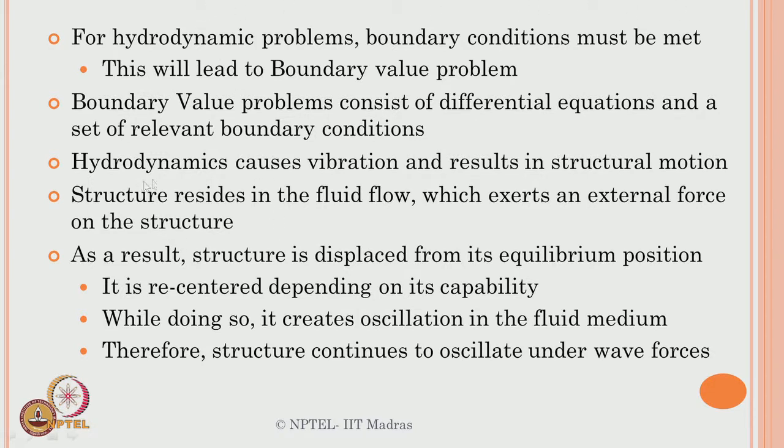Hydrodynamics actually causes vibration. The moment it causes vibration, it will result in a structural motion. The moment the structure starts moving in the regime of fluid flow, there is an external action acting on the member. Now, this structure will be displaced, whether the structure is fixed, floating, or compliant, there is always a displacement on the structural member, which is a result of the external force acting on this member, which arises essentially from the vibration caused by hydrodynamic effects.